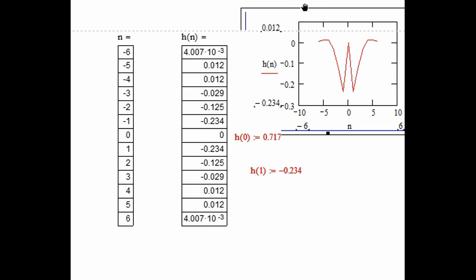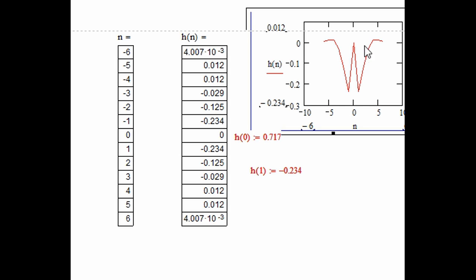And an interesting thing, and you can go into the theory later, if you do a Fourier transform on this one, if you take this time domain into the frequency domain, it will actually show you the Bode plot for your filter.